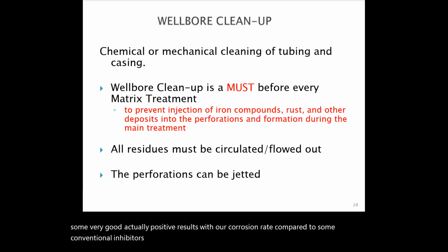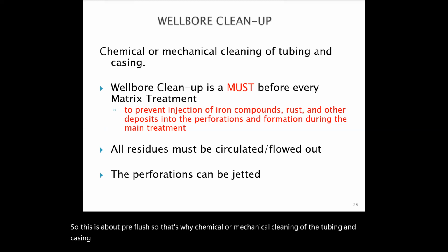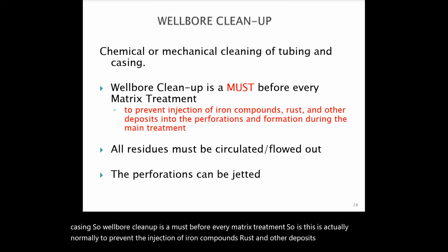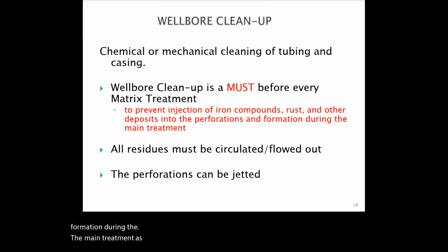Okay, so this is about the pre-flush. That's chemical or mechanical cleaning of the tubing and casing. Wellbore cleanup is a must before every matrix treatment. This is normally to prevent the injection of iron compounds, rust, and other deposits into the perforation and formation during the main treatment. As you know, the availability of iron can cause creation of sludge, and also can trigger other precipitates.